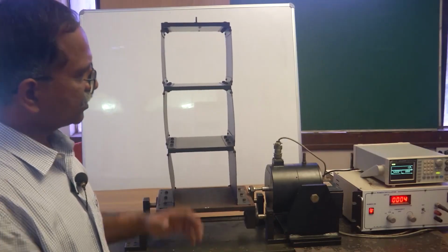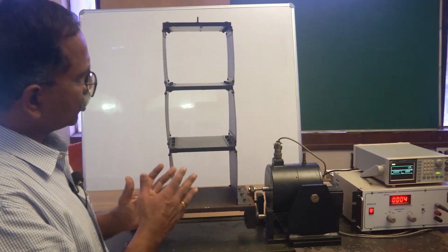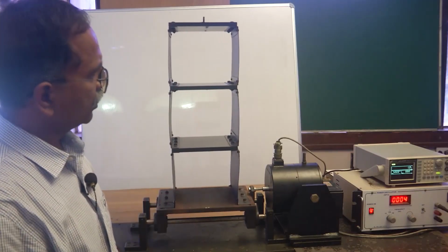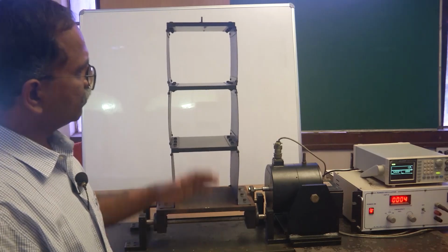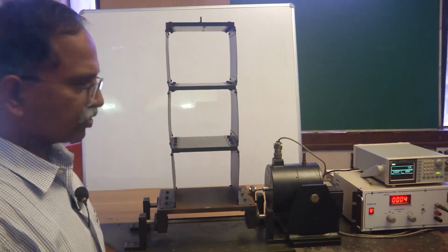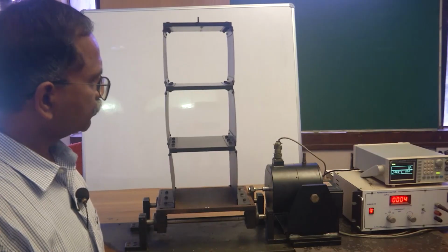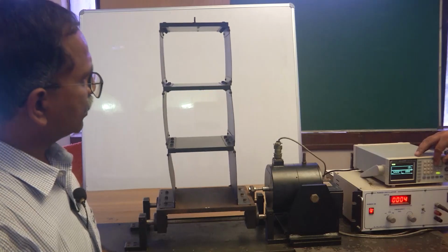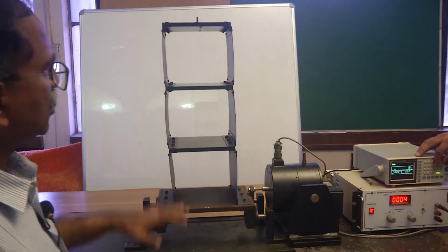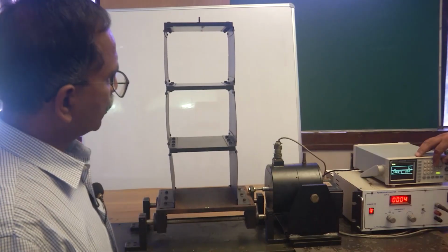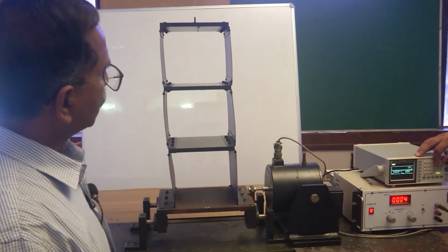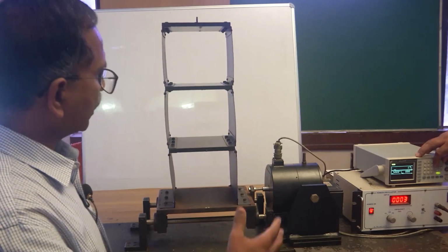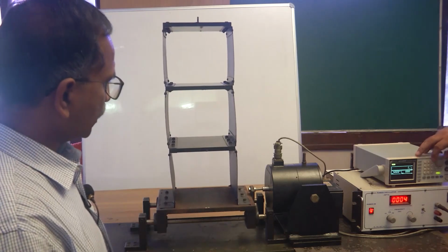So now this is basically indicating the first mode response, and this is the resonance that we are observing here. Okay. When the system vibrates at its resonance, the mode shape corresponding to that natural frequency is exhibited. So the operational deflection shape which we normally talk about is actually matching with your mode shape corresponding to the given natural mode. Yes. So now we will shift our frequency in steps and check at any other resonance that we observe. Now obviously this is a 3-degree of freedom system, and we expect 3 different resonances here, and so let us see whether we get another resonance by increasing the frequency and scanning it past the second natural mode.